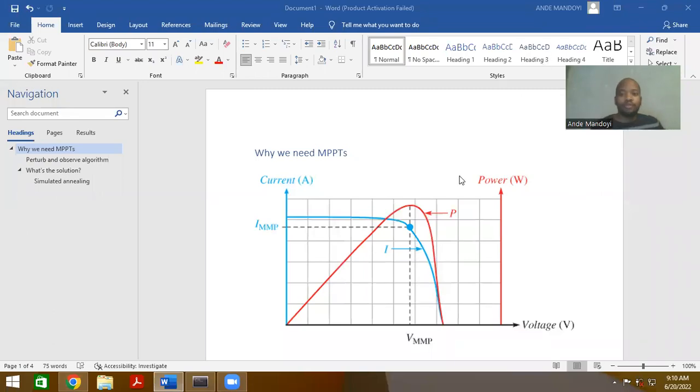Hello. So in the previous lectures, we looked at buck converters, how to linearize them, and tune PIDs for buck converters to essentially get constant voltage out of them throughout the load range, and all of that. And right now, what I want to discuss is the concept of maximum power point tracking. And this applies to solar panels because we're essentially going to use that buck converter as the first stage of a solar charger for the batteries of the car, right?